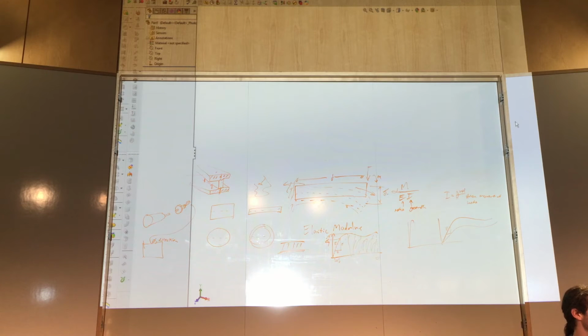Like on the MTM machines, the way they dealt with it, and Nani could probably talk about it better, but they put some flexure into the structure that's supporting the shaft. And I think they heat it and move it back and forth in position to align them and get them centered. On a precision machine doing high accuracy silicon wafer work, they just machine it perfect, and you pay for it. That's why it costs something like $100,000 per axis.